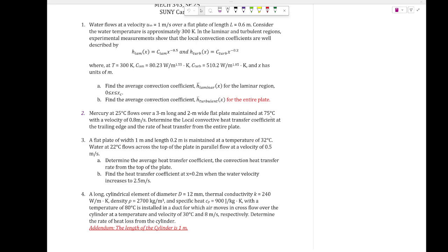Now, when you're measuring those two, you have to understand it needs to be at a certain speed. The speed of the fan that is connected in the wind tunnel. You remember you had a control over there. There's a knob. Do you know where the knob is? Able to find it easily? It's just on top of that somewhere. Okay, so the knob needs to be in a certain position. Whatever that position is, you don't need to use the period to find the velocity. But whatever the velocity, that is the one velocity you'll be using to fill out these two tables.